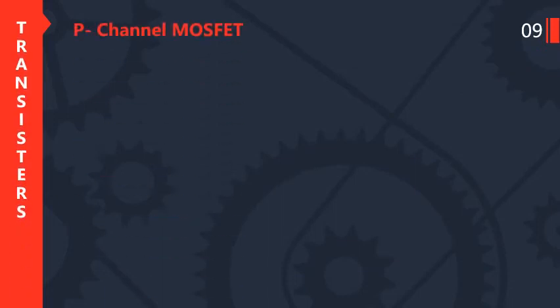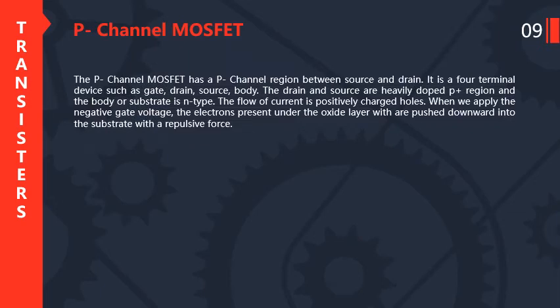So first one is P channel metal oxide semiconductor field effect transistor, in short MOSFET. The P channel MOSFET has a P channel region between source and drain. It is a 4 terminal device such as gate, drain, source and body. The drain and source are heavily doped P plus regions and the body or substrate is N-type. The flow of current is of positively charged holes.